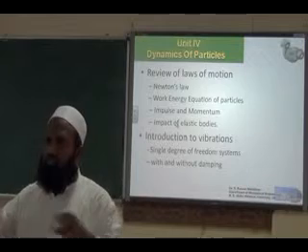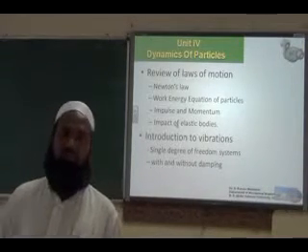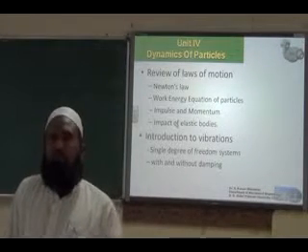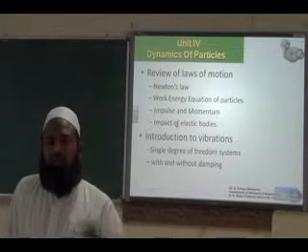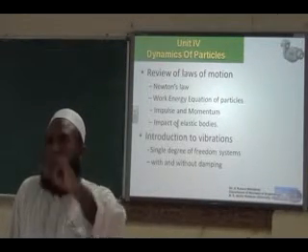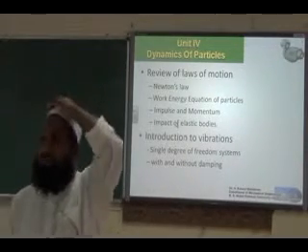Then how much distance it displaces. The distance of displacement is called amplitude. So the frequency and amplitude are two important parameters. Okay, so you have to find a particular frequency at which your amplitude will be maximum. What is the condition? Resonance.